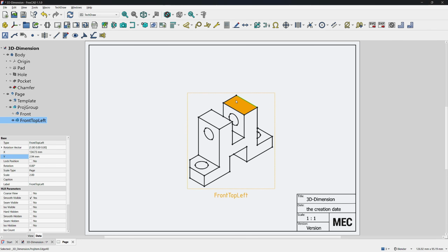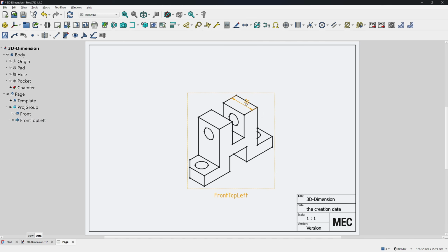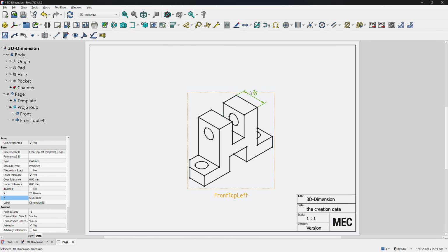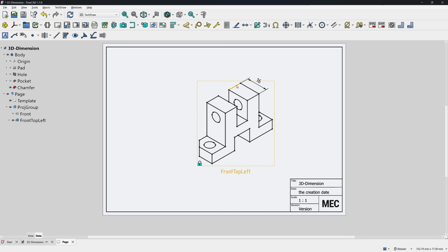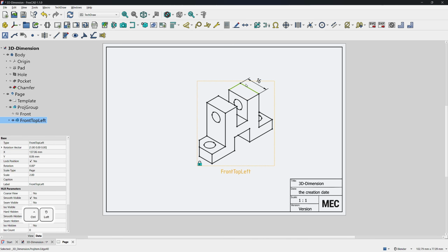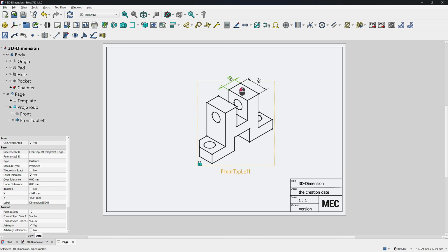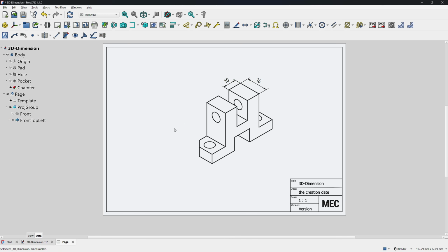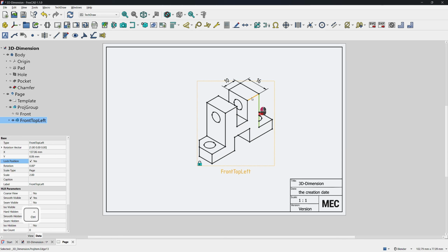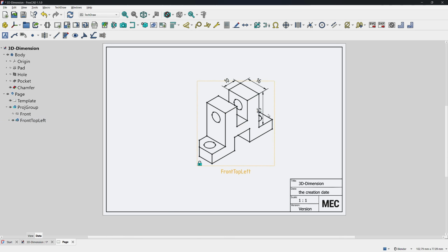First, select 2 lines. Then click on this tool. Then it will add a dimension. The first edge is the dimension direction, and the second edge is for the extension line direction. And then we can change the sequence to select these 2 edges, and we will add a length for another edge. Okay. Let's continue for this edge. The first edge is which we add length, and the second defines the extension line.